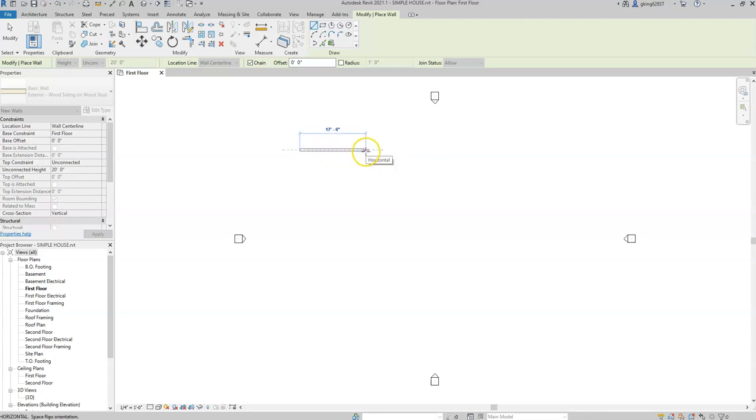As you'll see, I have some dimensions to help me approximate how big my walls are going to be. Also, you're going to see that I have a blue dashed line. That blue dashed line is very helpful because it has me at a horizontal snap, or a horizontal constraint. So I know that I have a perfectly straight, or horizontal, wall. But if I wanted to make an angled wall, I can just move my cursor up and it gives me my angles. So you're not just confined to doing everything at 90 degrees, of course. You can make curved walls, bowed walls, angled walls, whatever you want.